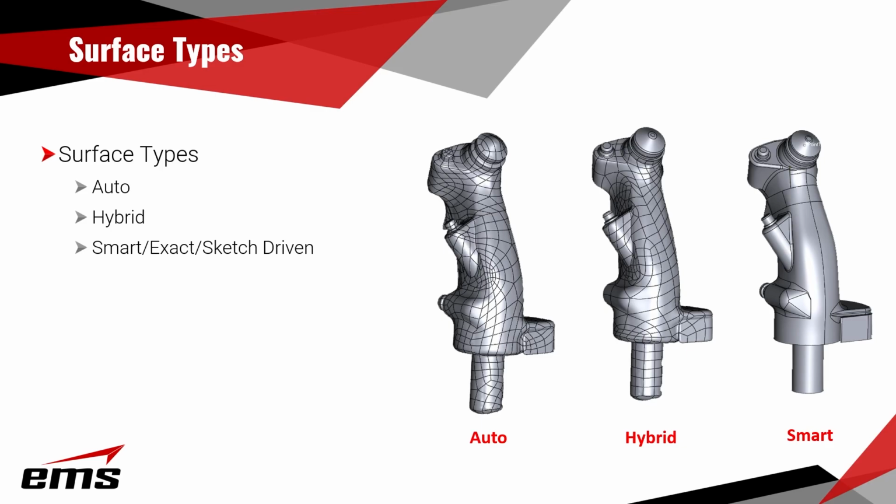But for now, let's just look at the differences here and talk about them. First off is the auto surface, and that's this one you see here. What you basically do is you 3D scan your object, you clean up the mesh, you try to make it what we call watertight, meaning it doesn't have any holes and it's closed up. So you'll do some cleanup of the data, and then you run a command called auto surface, which basically fits this quilted patch of surfaces through it.